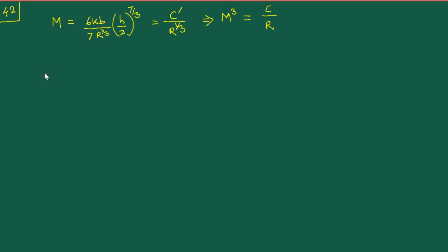So what we'll do is consider this. It may seem like for apparently no rhyme or reason I'm doing this, but you will get the hang of it in just a minute. So dU dash, where this U dash is the complementary energy, and we're taking the differential of that. I want to represent it in this fashion. This is very much reminiscent of the things that we were doing as part of our proof of Castigliano's theorem on deflections, except that now we are writing the differential not in terms of the applied force, rather in terms of the bending moment.